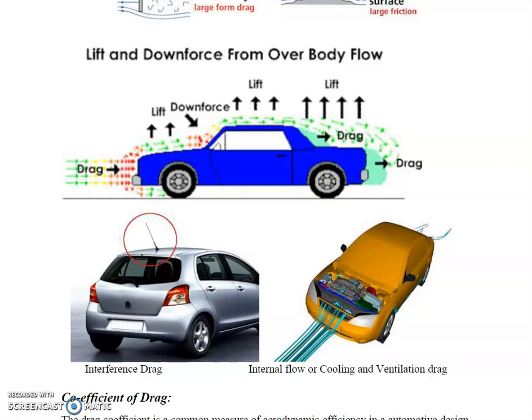It is the sum of all energy losses produced when the air passes into, through, and out of all vehicle systems requiring or permitting airflow. The engine cooling flow, which is primarily an internal flow component, plus the passenger ventilation flow, and any internal flow required to cool brake or other mechanical components contribute to internal flow drag. So it is about 12% of the total drag.